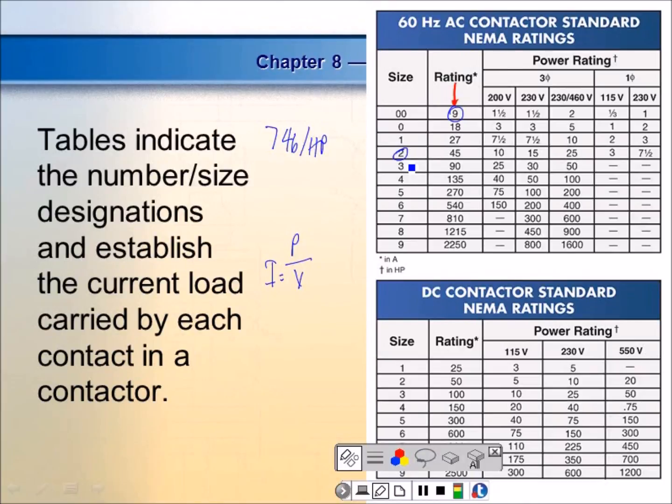And those are AC. These are DC contact ratings. NEMA, which is the National Electrical Manufacturers Association, these guys here set a lot of standards for us. Most of the things that NEMA sets are physical standards. The layout of the thing, right? How it's shaped. How do we mount it? Where the mounting screws are? What's the size of it? So this motor over here has a certain NEMA frame. What that means is, if I buy a motor that has the same NEMA frame number, the motor's going to mount the same, and the shaft's going to be a certain size length, right? Y'all understand what we're saying?